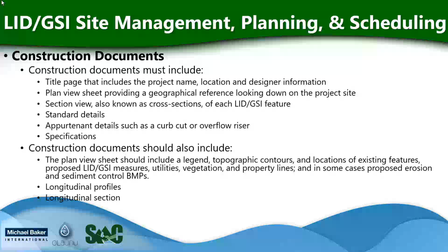Construction documents should also consider including the plan view sheet, including a legend, topo, contours, locations of existing features, utilities, vegetation, and property lines, and in some cases, erosion and sediment controls. They should also include the longitudinal profiles and the longitudinal section, which pertains to a section along the long axis of a structure.